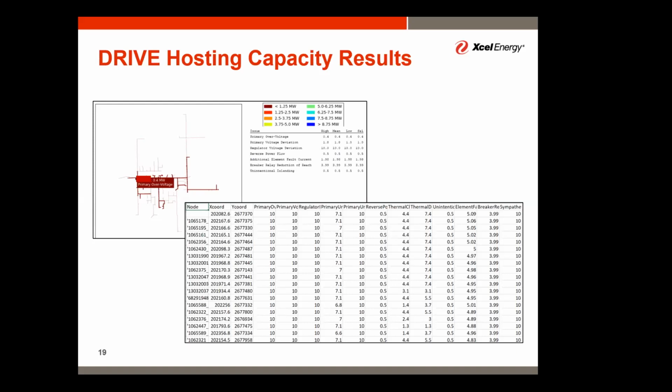This is Timothy from Cooperative Energy Futures. I'm not sure I have a direct answer to the question, but the piece I'm struggling with is the correlation or lack thereof between the hosting capacity map, which seems primarily to look at the node level and feeder level voltage data, and the types of information we ultimately get from pre-application reports, previously called capacity screens, which also look at feeder capacity and substation capacity.